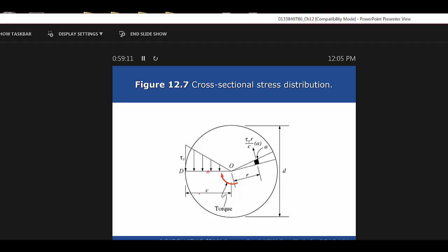So I think that's what's pertinent about that table. You're only going to be able to get it in increments of 1/16 of an inch. So if it's somewhere between 2 7/16 and 2.5, you need to step up to the 2.5. Or you could have your machinist turn it down to 2.48. Really, do you want to do that work? Because then you're probably going to have to order a special pulley to put on it, because the pulleys tend to match the shafts. Actually, the pulley diameter might be 2.48, and then you have to press it on. It wouldn't be quite that big or that small, but you can press those on. Okay.